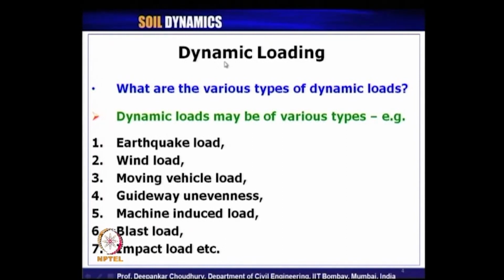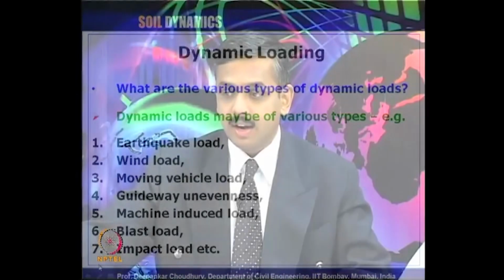We have seen examples of various types of dynamic loads like earthquake load, wind load, moving vehicle load, guideway unevenness, machinery induced load, blast load, impact load, etc. But that does not mean all time dependent loads are dynamic. There can be live load also which is not dynamic in nature.